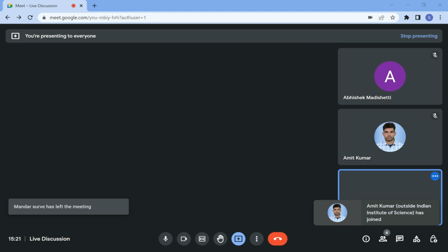No. So always remember that in the final drawing, when the line is inclined to both the planes, we never see the true angle. We only see the apparent angles. And since they have given the angle of front view and top view, we are saying that we can see them in the drawing. So they have said that end A is 10 mm above HP and 15 mm in front of VP.